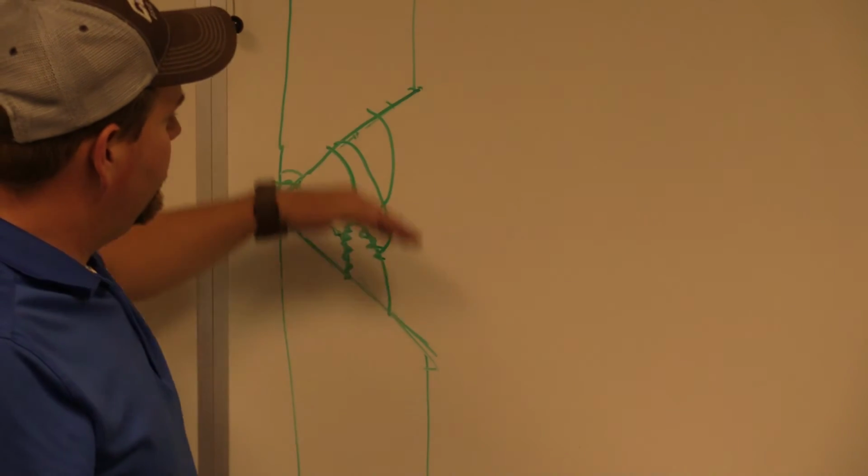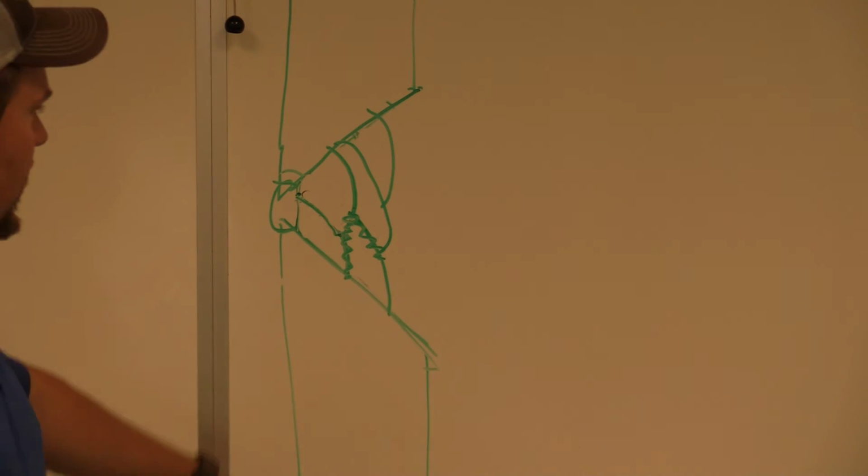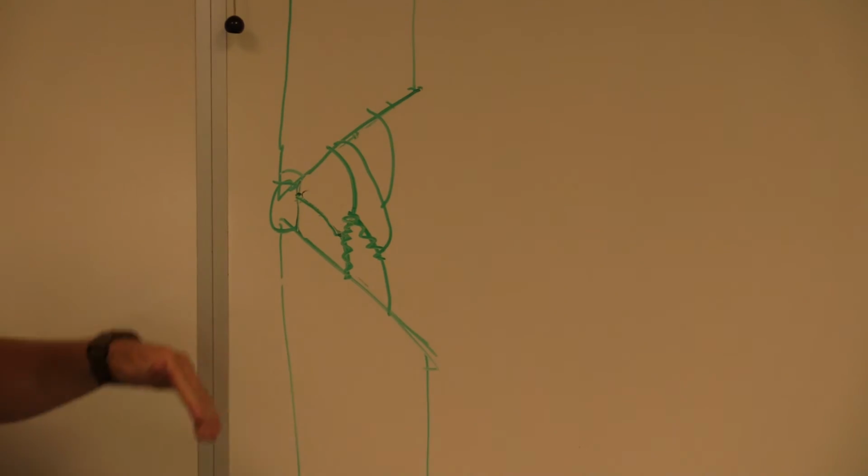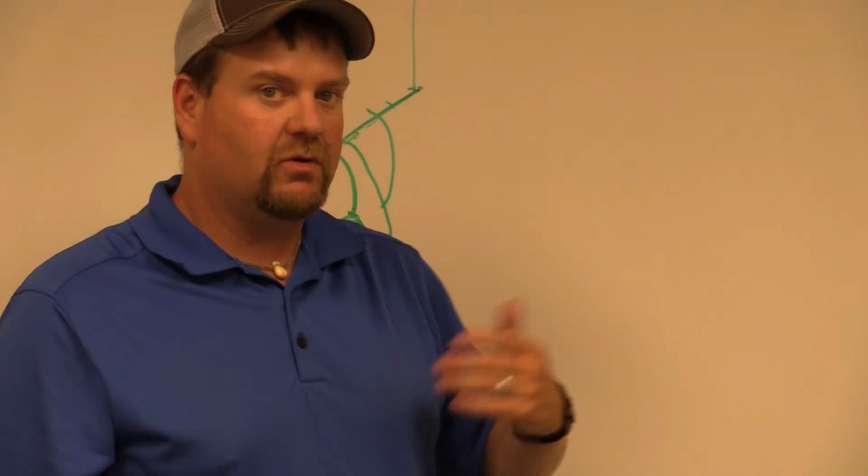We want to make sure that everything we're welding over has been ground, but we don't have to clean the entire thing down every time. Okay, that takes up a lot of time, so we have to start learning how to shave some time and be efficient, especially with MIG welding.